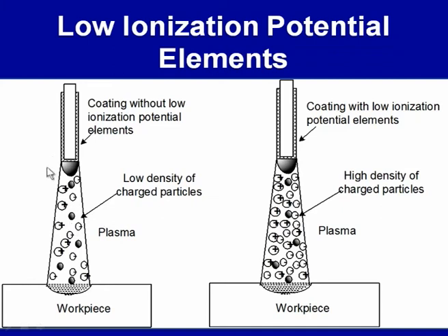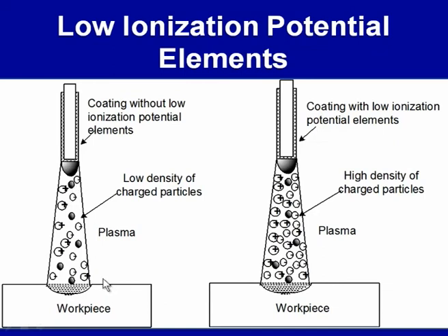This makes the flow of current between the electrode and workpiece difficult, and that is why the stability of the arc becomes poor when bare electrodes are used, especially when using AC current, while even with the bare electrodes the use of DC current helps to maintain a reasonably good arc.